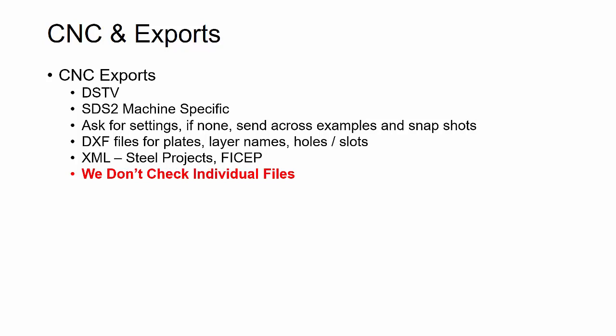Now, you'll see that I have it marked in red here. We don't check the individual files. So as a detailer, we're not experienced in actually opening up the individual CNC files and inspecting and checking them. What I do tell our detailers to do is go through the setups with the fabricator and make sure we conform to those standards. But then from there, we're expecting the fabricator and the production control to review those individual files.